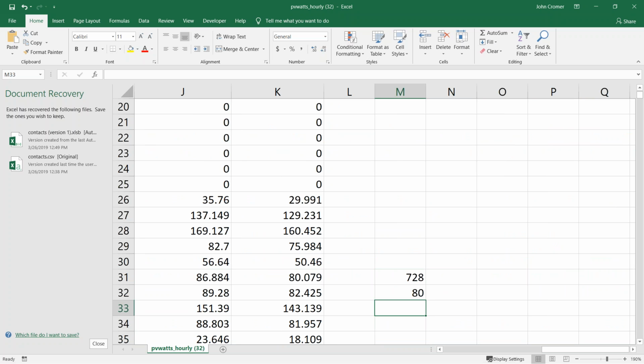So let's assume that the underside of the panel is all diffuse light. And so what we're saying is maybe the bifacial panels will boost the performance of the array by about 10%, and they cost more. So if you're trying to be cost effective, you don't really go for bifacial panels.